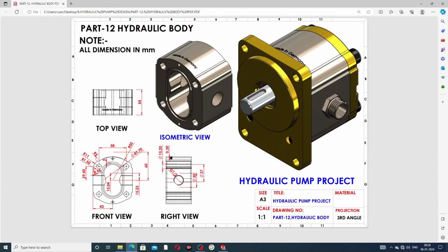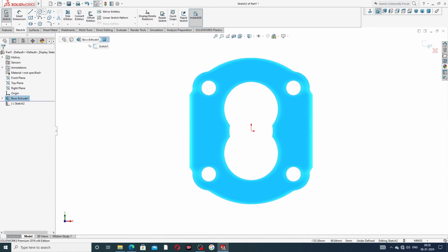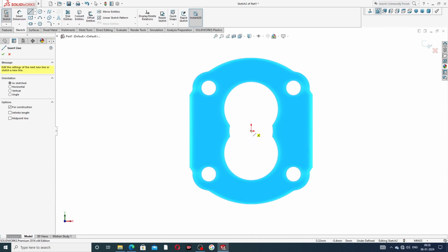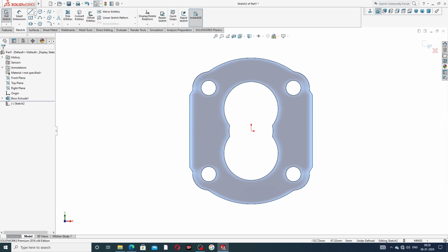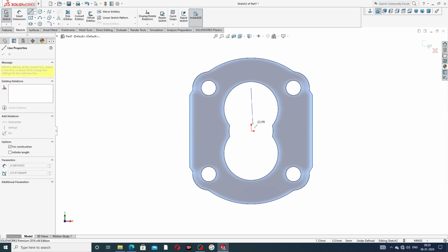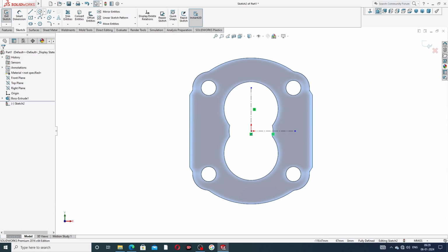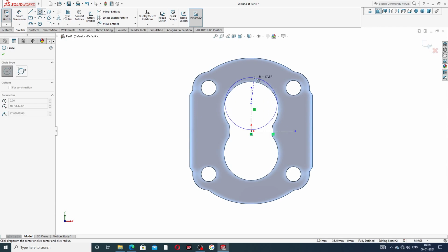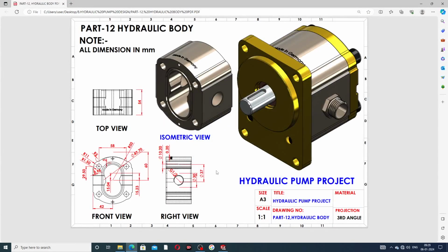Next is a cutout drawing here. Select this face, sketch, normal, and draw a circle. This line is drawing here, and this. And this circle is drawing here. Draw this, and this circle has a radius of 47.7, and the center point is 15.04.